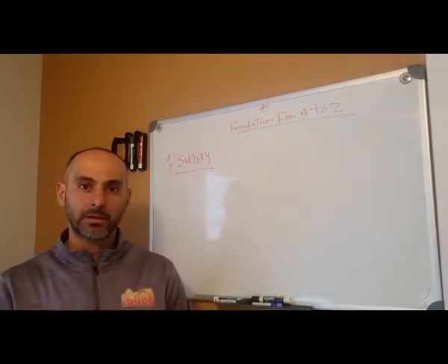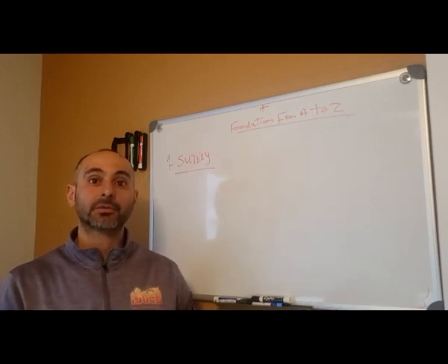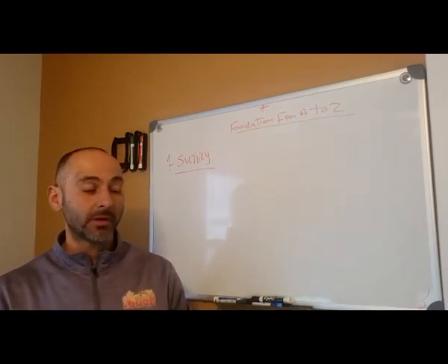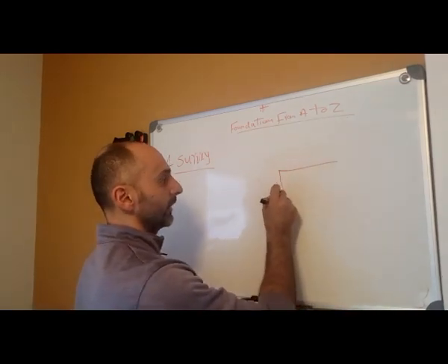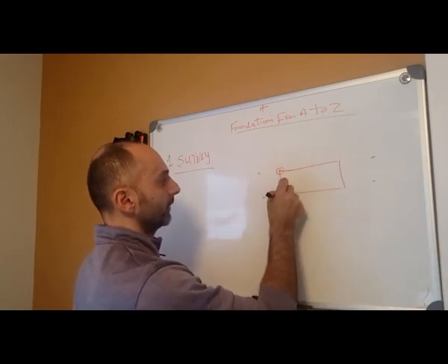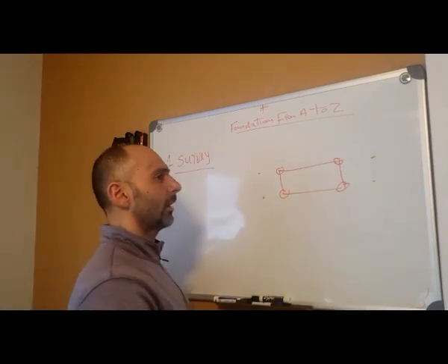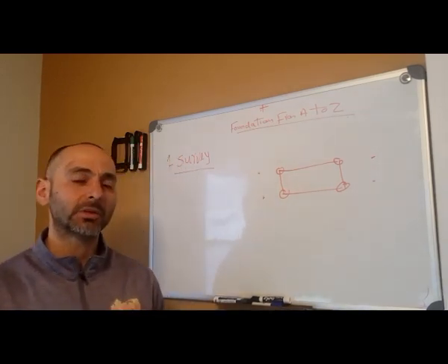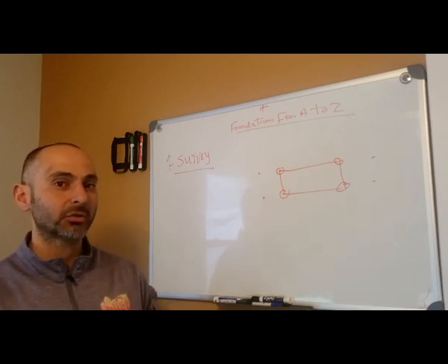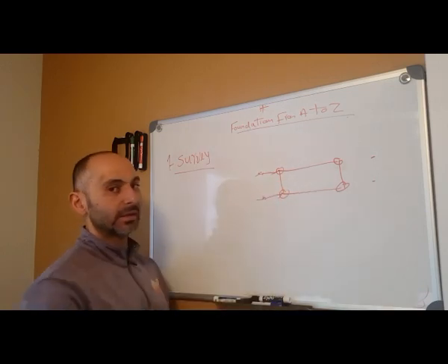Make sure you have a good surveyor on your team from the beginning of the project. Make sure your surveyor does construction work. Not every surveyor does construction work, so ask the question before you hire a surveyor. Okay, so two things for the surveyor. One, they're going to give you offsets. Offsets of the building corner, usually 5-10 feet. Ask your contractor how much offset you need. With a basement I do 10 feet, with a crawl space 7 feet, because there's not much soil to disturb. So make sure you speak to your contractor and ask him what the offsets are.